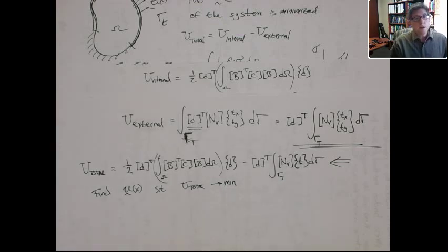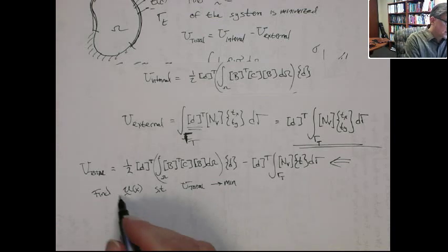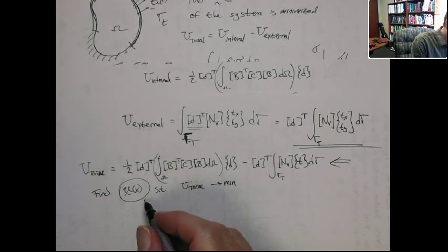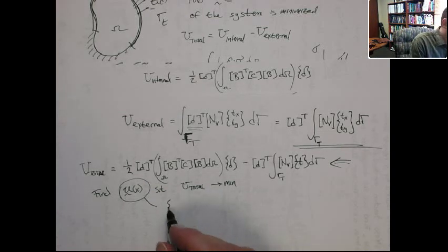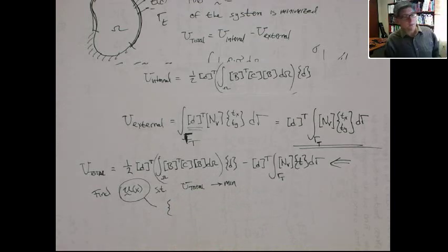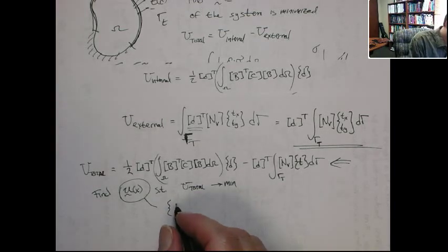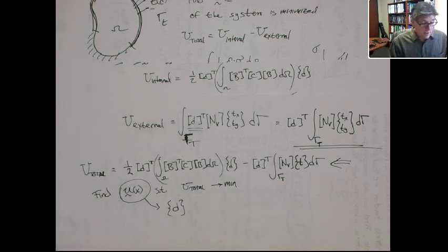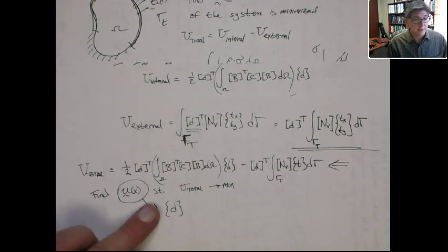All right. Now, in this problem, I've already introduced the finite element interpolations. So what was once like an infinite set of values, spatially, right? You had an infinite dimensionality there, at every point. Now, looking at all possible displacements is the same, in the discrete sense, as looking at all possible values or combinations of values for the nodal unknowns, the U1, V1, U2, V2, and so on and so forth, okay? So we want to minimize this with respect to these.